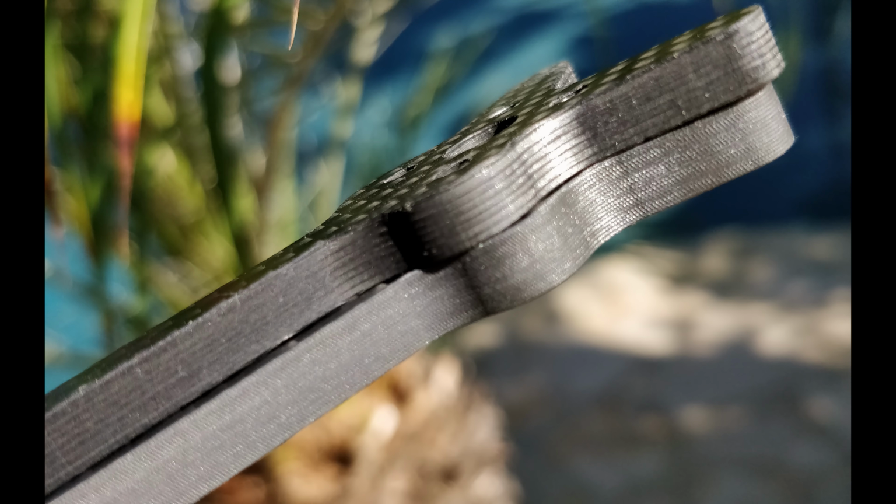The other process of making these carbon fiber sheets is that you put it together with the resin and then bake it under pressure and heat. You get everything to bind and then cure and laminate together. And if it's not good quality resin, it will cause delamination of the edges of the arms, or can potentially make the torsional twisting motion on the arm worse or weaker, and you can run into a whole bunch of issues there.